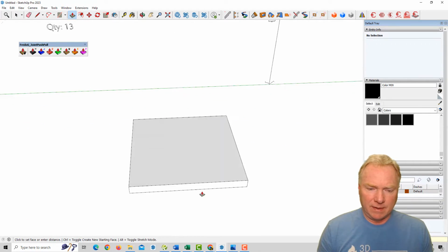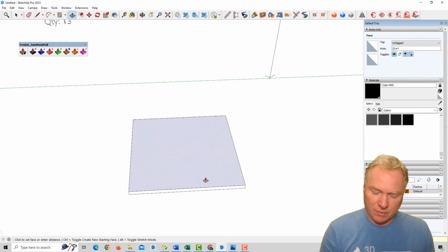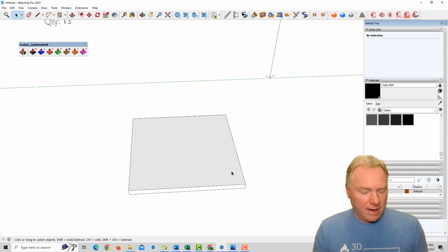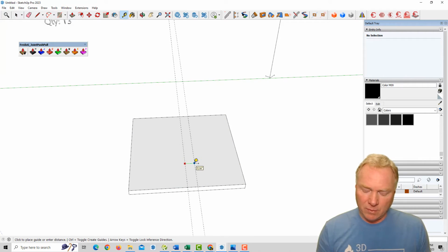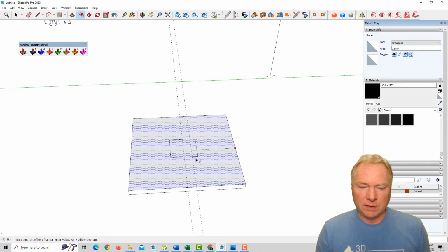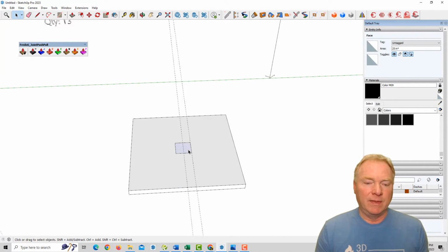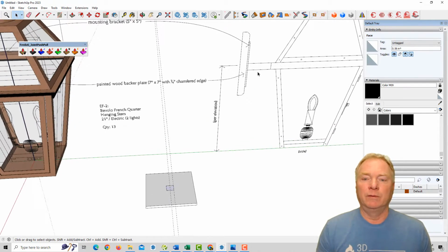If it's even that thick, maybe it's down 1/8, maybe it's a 1/4 inch plate metal. All right, I want the midpoint of this, because I'm going to do the offset here for a 3/4 inch post. So I'm going to say 3/8 of an inch. Use the offset tool to close into that guide, and that leaves me that 3/4 inch post.